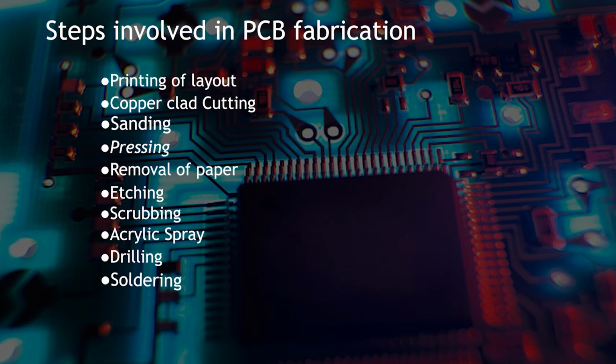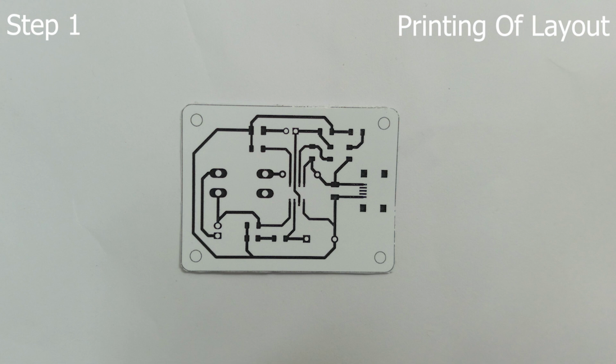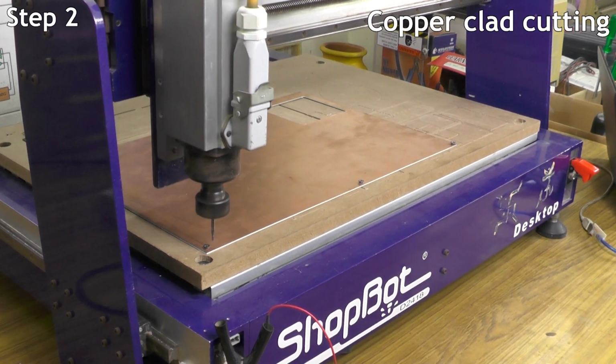Steps involved in PCB fabrication: printing of layout, copper clad cutting, sanding, pressing, removal of paper and needling, etching, scrubbing, acrylic spray, drilling, soldering. Step 1. Printing of layout. The first step involves printing the circuit layout onto a special transfer paper, photo paper, using a laser printer. The layout represents the copper traces, pads, and other components' locations.